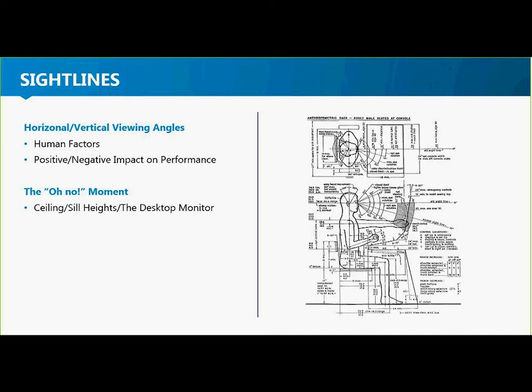But from a general perspective, if you're at the 50,000-foot view about how I can employ some best practices with sightlines, one of the things that I find a lot of my customers miss when they're either designing a new facility or, for example, implementing a video wall solution in their command center, and maybe they're working with an architect, maybe not, is this: where you're sitting at the command console with a monitor in front of you, there is a distance between the floor and the top of the monitor at that console.